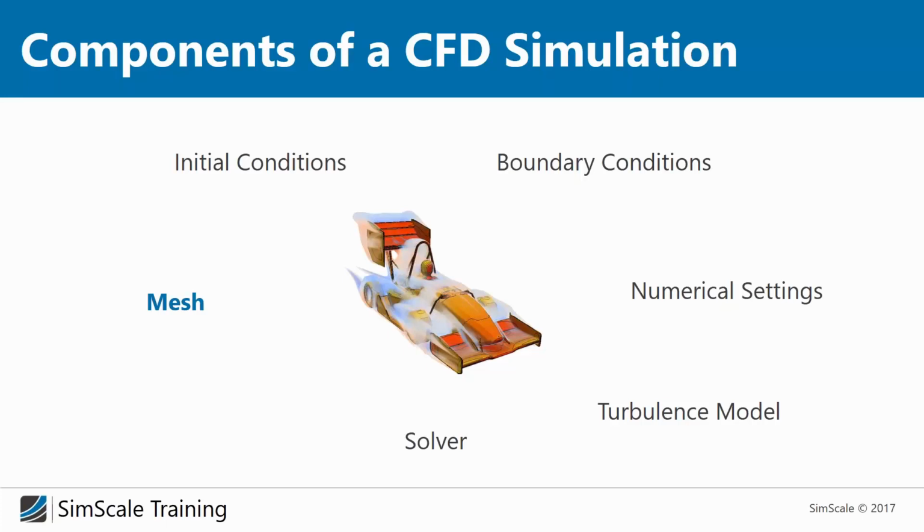And since there is not one single solution, here we should refer to a concept called mesh independency, which means if you do a CFD simulation, for example, of a front wing, and let's say use a uniform mesh, which means you have the same cell size everywhere, and you would start now to refine the mesh and compare, let's say, the same simulation setup, the same problem, with 10 different meshes which have different levels of fineness, then you would see that at the beginning when your mesh is very coarse, you will have a lot of change, and every time you refine the mesh the result is changing. But from a certain point you will see that even making the mesh finer is not really changing the result.